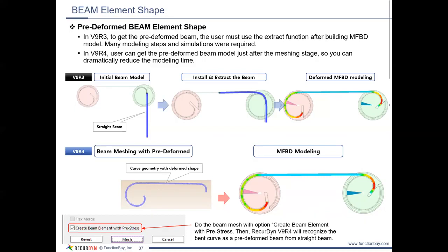And in some cases, it's really helpful to be able to start out with the beams in their deformed state and already pre-stressed. We can see one example here where we're using these beam elements to become a cable. And we have this cable acting between two rollers.